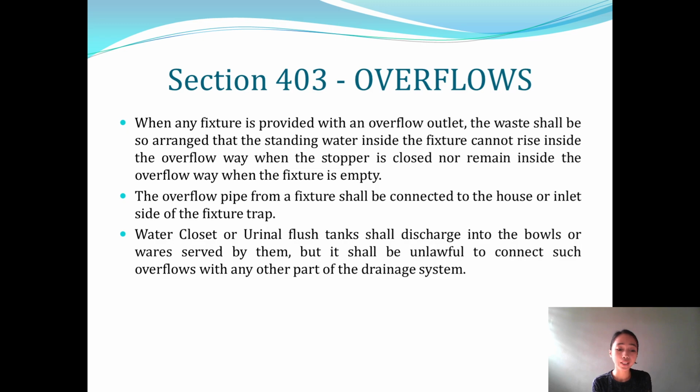To protect the drinking water supply, all plumbing fixtures should be designed so as to ensure that incoming water is delivered through an air gap. Tap water should be appropriately matched to the fixture that it is intended to serve. When installed, all water delivery outlet fittings should have an adequate clearance between the water outlet and the spill level or water overflow level of the fixture being served.